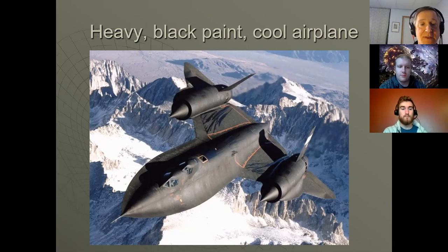So that convective heat coefficient is really high, but the density is really low. So there's not much media to work with. There's not much air to work with. So it relies on radiation, and it has emissivity to work with. And to improve emissivity, you paint things black.